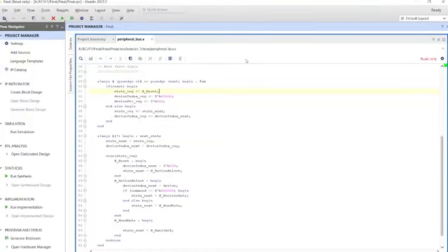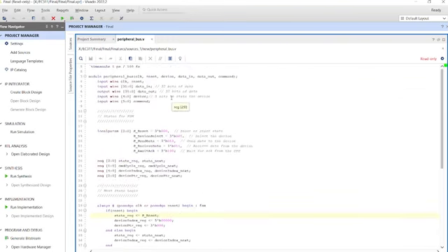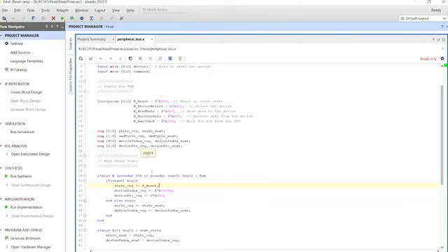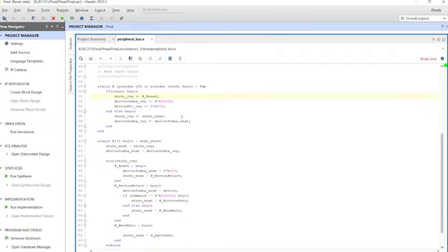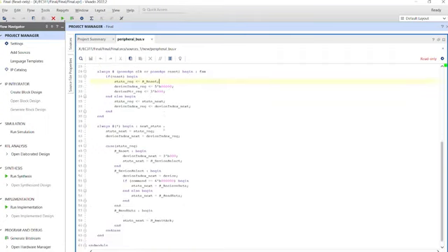One of the files I worked on was the peripheral bus. A peripheral bus essentially allows the processor to read in and write data to whatever the microcontroller is attached to. In our case, it's the LEDs on the FPGA board. As you can see, it's a finite state machine. If the reset button is pressed, then all the values reset. Otherwise, the state just moves to its next state.